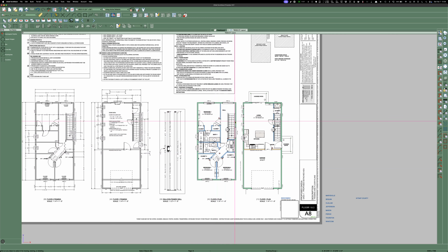Along the stairs, you always want to balloon frame, because if you don't, you'll have a hinge. And I've seen houses built where all the walls are built with pre-cut 9-foot studs or 10-foot studs, and then they joist. And at this point here, they'll just run whatever your joists are, 11 7/8. They'll just run a couple rim boards with blocking between them, and then they'll put subfloor all over this and a strip of subfloor 5.5 wide, and then they'll put a wall on top of that, and they think that's good. But this section here has a hinge point, and in any big seismic movement, that might become a problem.